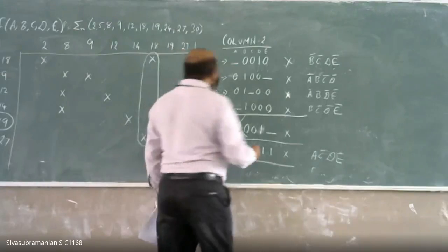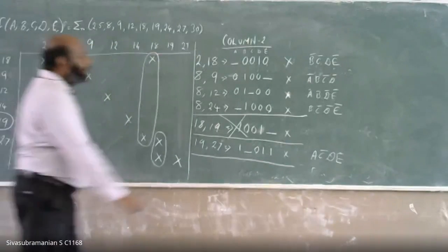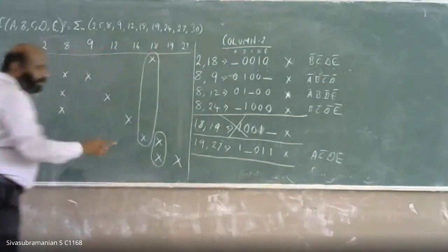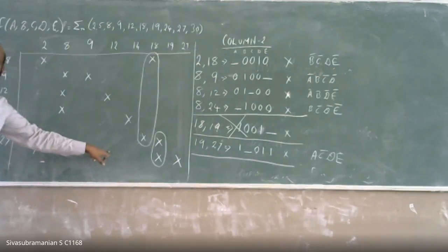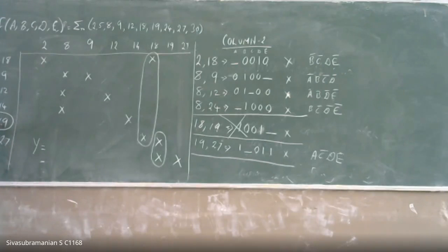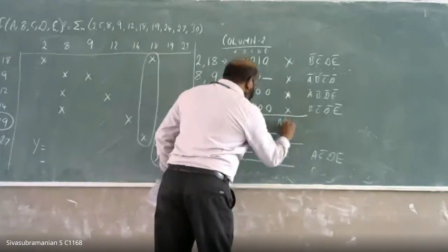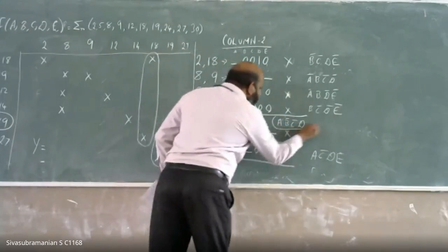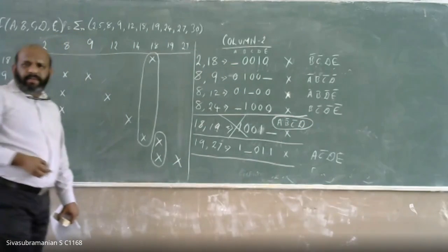Finally, write an equation like y is equal to, put all the 5 terms with a plus sign in between, and that now gives you the solution. Finally, mark a statement like: prime implicants are shown above in the equation, and the non-essential prime implicant is 18, 19. What is that 18, 19? A, B bar, C bar, D is my non-essential prime implicant. So that completes your problem.